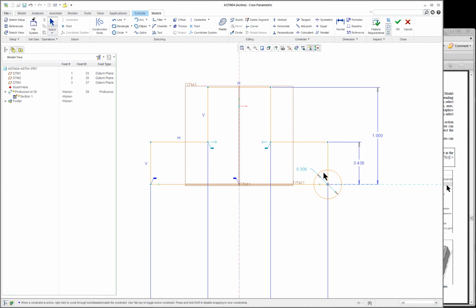Basically you have these sections over the top of each other. We've got to remove this. It can only have a continuous line or arcs around the object. So we want to get rid of something in here. And if we go up to the top here and click on delete segment, you can put your cursor and just pick on that, or you can actually draw through it and then middle mouse button. And you'll see that by removing those lines, we now have the shape that we want.